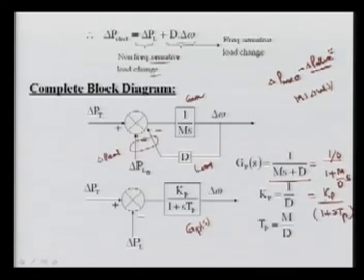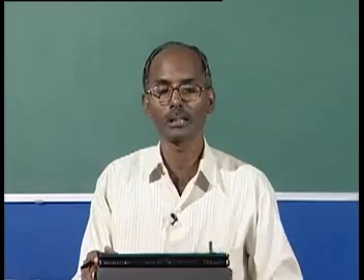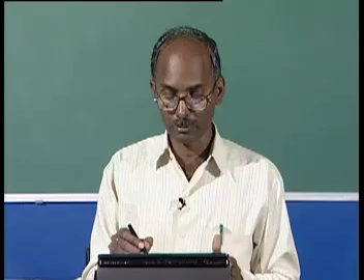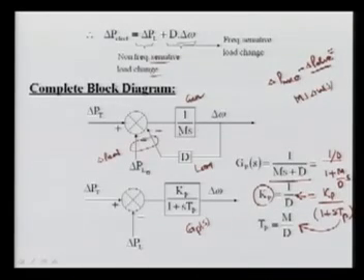So this Kp which we are getting is nothing but this value, and your Tp is M upon D. So this is the time constant of the power system, and this is the gain of the power system. One thing we should be very careful about, because sometimes H is given instead of M. Here we have formulated the power system with D, that is no problem because it is frequency dependent, we are using frequency directly, and here M is the angular momentum. Now we can also use another constant, that is the inertia constant, and let us see how it is related.